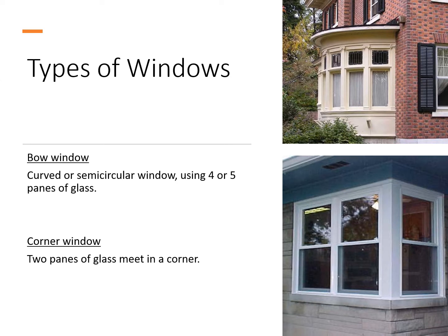Next is bow window. These are made of a number of windows and each window has smaller windows within. This type of window helps to reduce the intensity of the sunlight as a large glass pane is covered by a little woodwork. Corner window. In a corner window, two identical windows on adjoining walls meet at a corner. Corner windows can be treated as one unit or function separately.